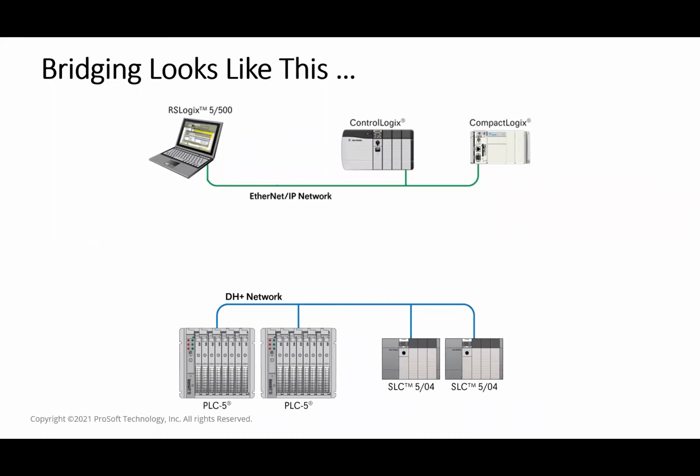Next slide, please. So bridging looks like this. Here you see two separate isolated systems, the old one on the bottom, the new one on the top. Both systems are running, but the old one is isolated. You can extend the life of that old functioning asset by bridging, right? You're not modernizing anything. You're adding connectivity to a network that wasn't connected in the first place. Now you have access to it and to its data.